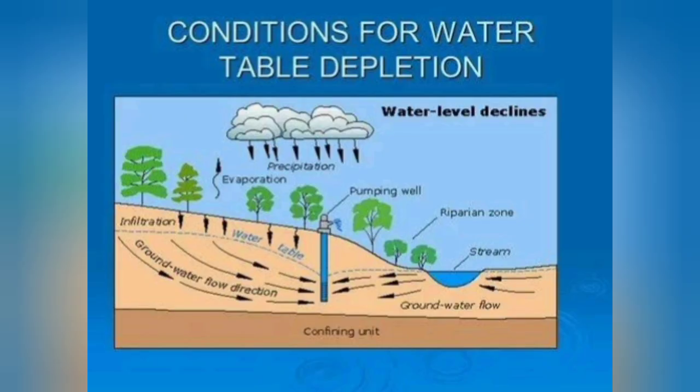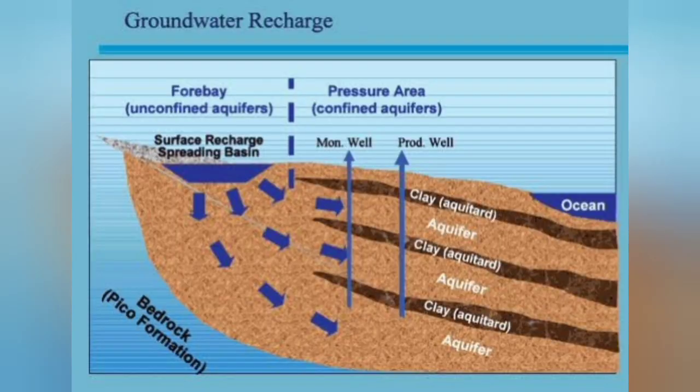So subsurface reservoirs located in suitable hydrogeological situations are generally environment friendly and economically viable propositions. The subsurface storages have the advantage of being free from adverse effects like inundation of larger surface areas, loss of cultivable land, displacement of local population, substantial evaporation losses, and also sensitivity to earthquakes.